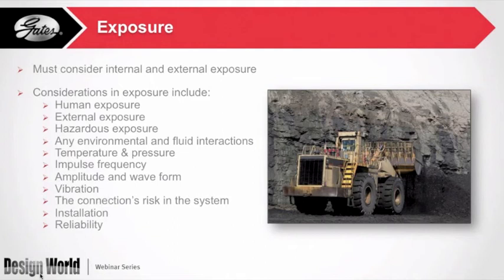Some of the external exposures and things to consider are human exposure. By human exposure, I mean the tank truck driver who tends to leave the hose hooked up once in a while when he drives his truck away. These things happen. If that's the case, or if it's a dock hose, we want to make sure we've got the appropriate breakaway coupling on that. Those things exist because people do some stupid things sometimes. We want to make sure that we think of the human exposure.